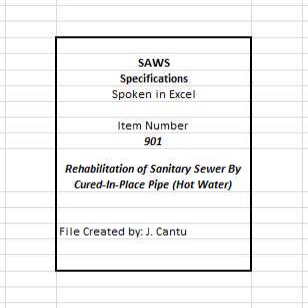901.6 Testing. 1. Chemical resistance. The CIPP shall meet the chemical resistance requirements of ASTM F1216, Appendix X2 except as modified herein. Table X2.1 of ASTM F1216 shall be modified as follows. It is required that CIPP samples with and without plastic coating meet these chemical testing requirements. Proof of chemical resistance test shall be provided to the engineer at least 15 days prior to commencement of work.